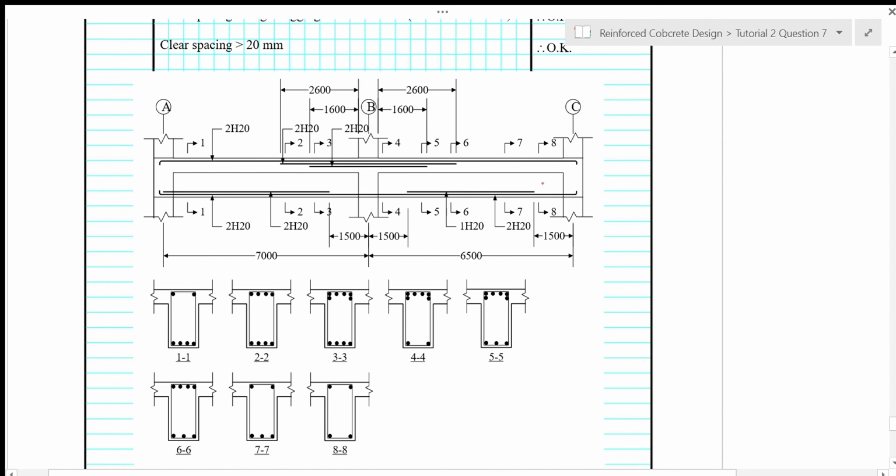As well as on this side, in the simplified detailing rule, we can reduce this to 30%, but we have 2H20, which is 66.7% of the total bars here, so it's okay. And then the distance you just calculate accordingly. So this is 0.3L minus AL. The same is for this distance as well.